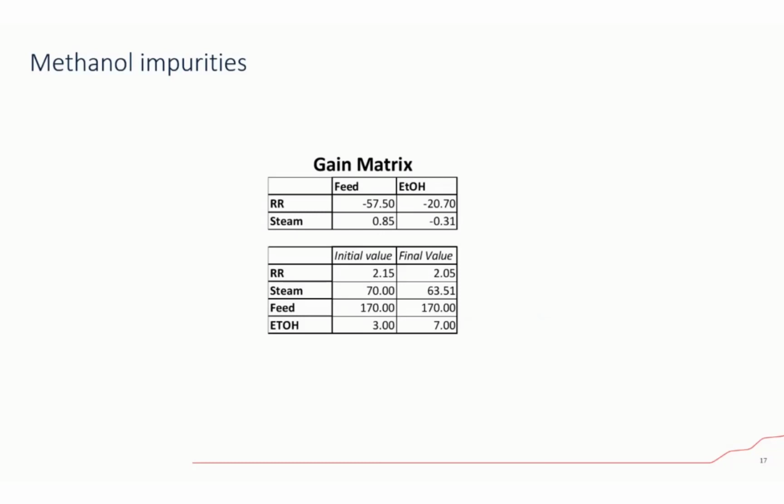One more question here. As we discussed in the previous webinar, and you emphasized during this call, maybe I want to bring it out. If the base layer PID control strategy is not optimal, do you think APC can help, or should we go back to the design and try to fix the control strategy first? Well, definitely you should try to make your base layer control as good as possible. That would be my advice, to go and do it right from the beginning.